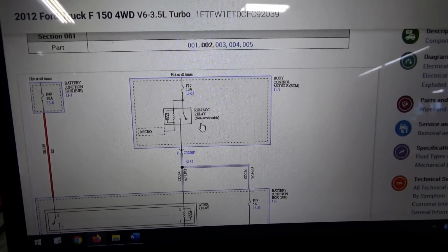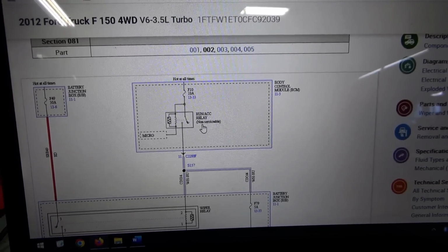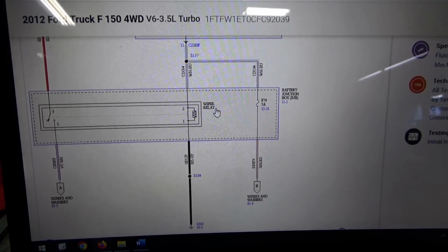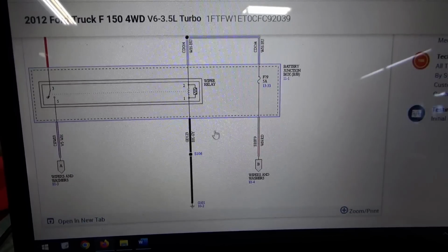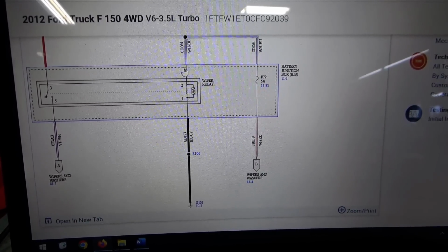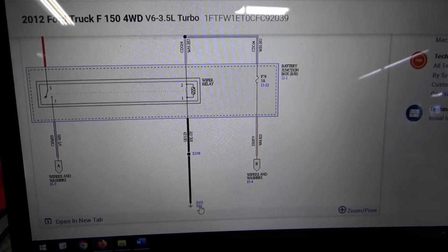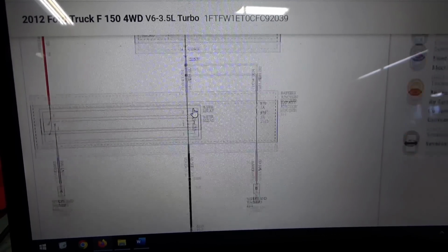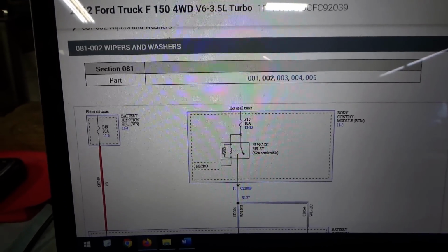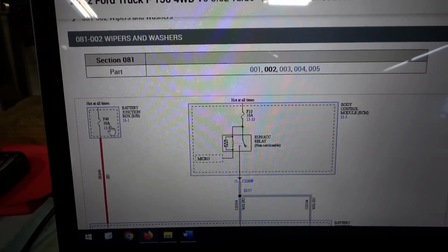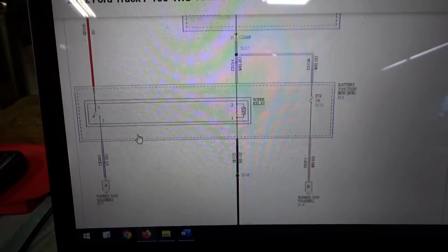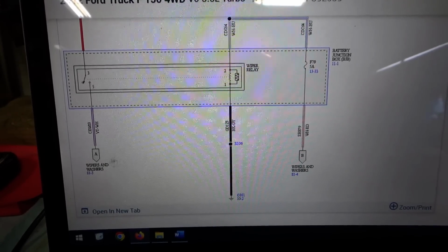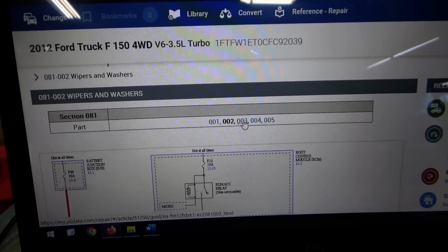There's the BCM, so run accessory relay. Then in the battery junction box we have a wiper relay. And apparently when that turns on, it'll send power through the control side of the wiper relay straight to ground. So this should turn on at the same time as the run accessory relay. And then battery junction box, fuse F49, 30 amp. That clicks, sends power on this violet and white wire to A. So let's go to the next page.